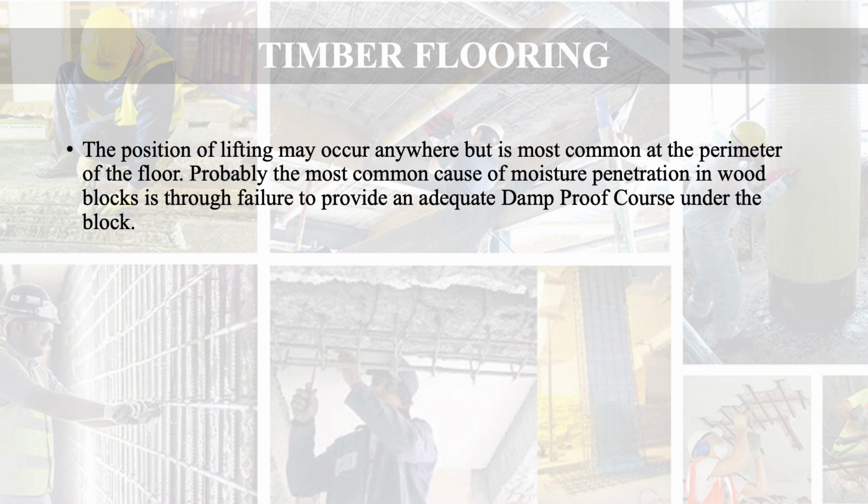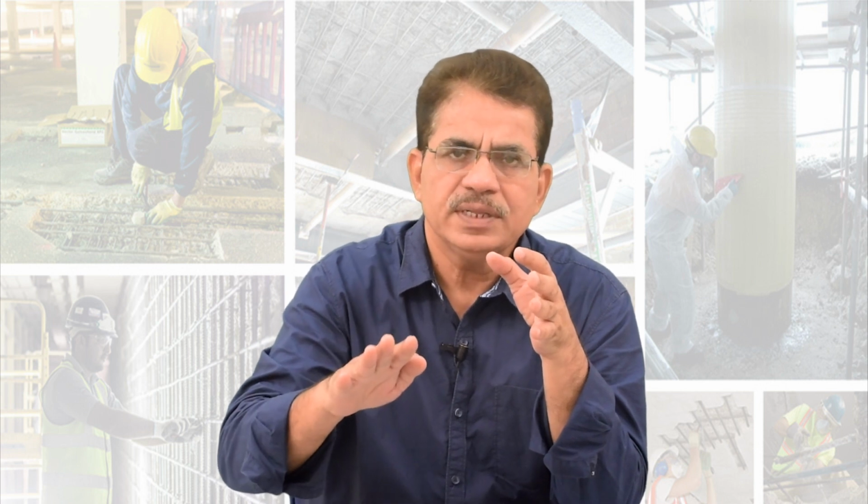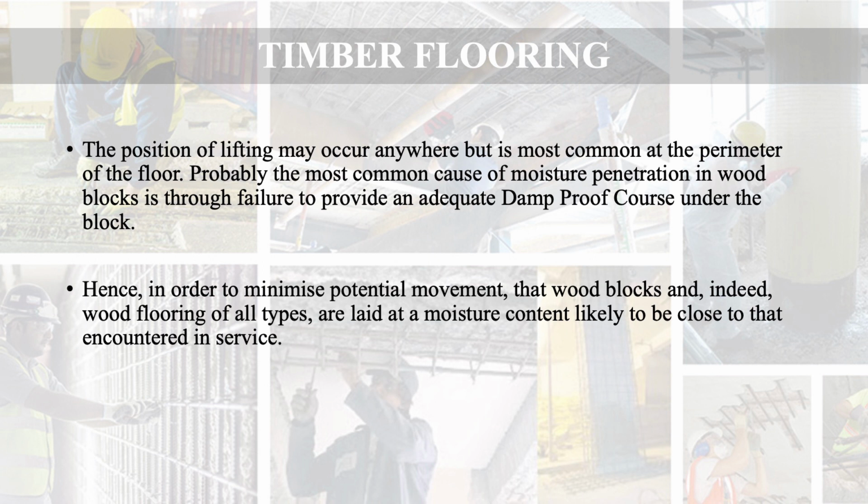The position of lifting may occur anywhere, but it is most common at the perimeter of the floor. Probably the most common cause of moisture penetration in wood blocks is through failure to provide an adequate damp-proof course under the block. If you want to avoid this situation, then we should provide an adequate damp-proof course under the blocks. Hence, in order to minimize potential movement, wood blocks and indeed wood flooring of all types